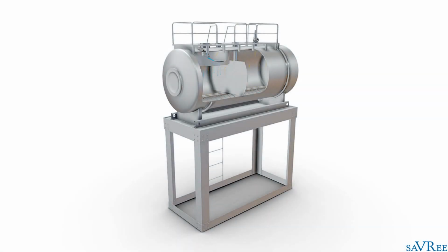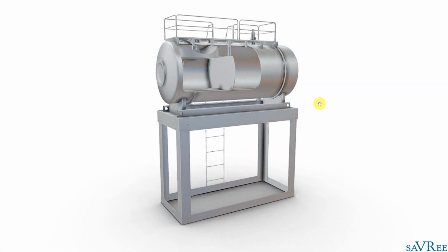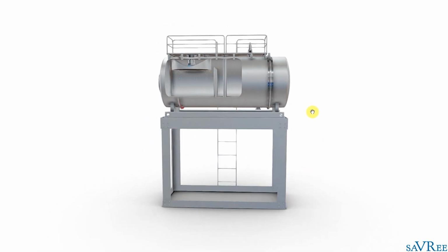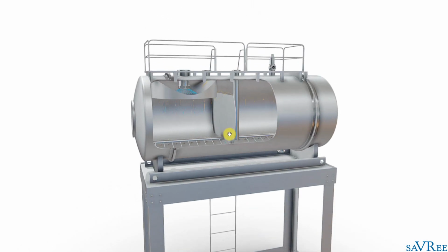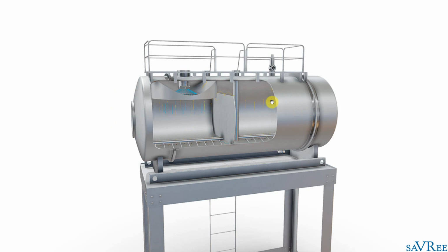So here is a Deaerator. There are several different designs that you might have. Notice that the Deaerator itself is sitting on a raised platform. You'll often find Deaerators quite high up in power stations, and the reason for this is it gives the pumps which draw from the Deaerator a positive head of pressure.